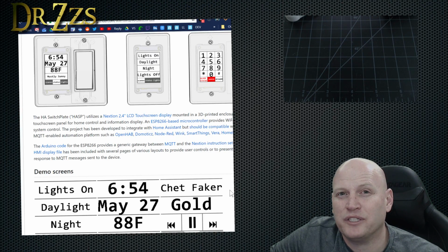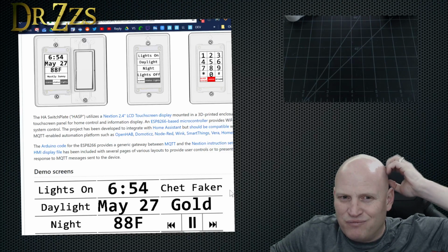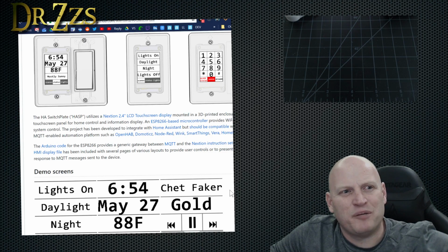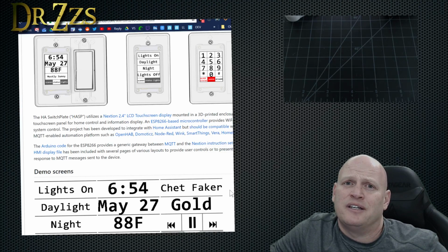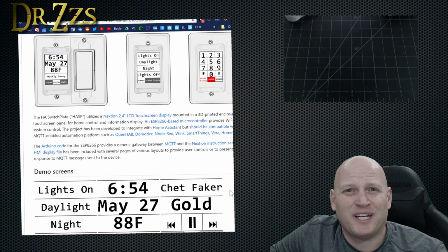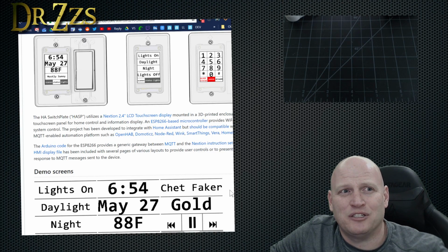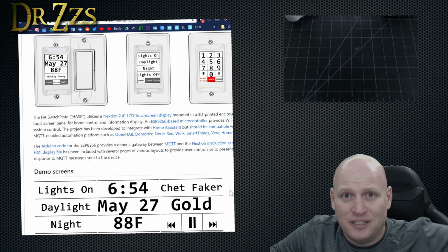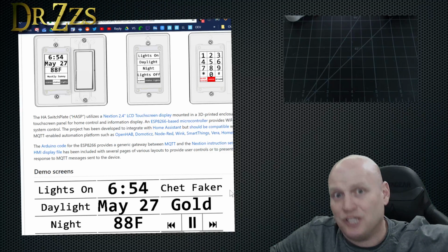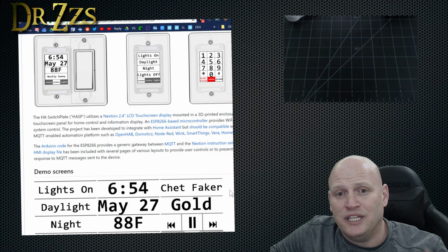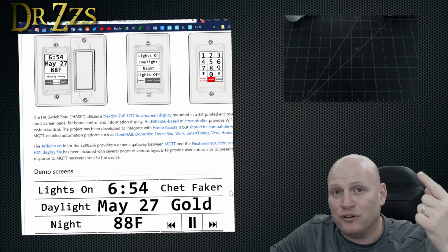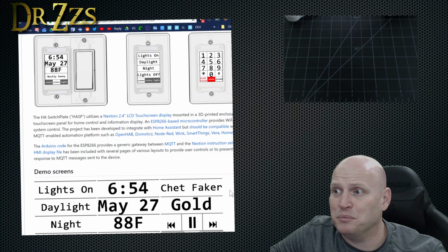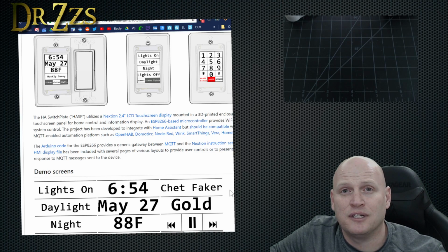I don't think you're going to find a smart switch. You've probably seen that video where I kind of tried to explain that. If you open up your switch box and all you have is 2 wires coming to your regular light switch that goes on and off, then you're going to have a real problem trying to get anything smart in that box, because what you have in that box then is just hot, really. It's a hot wire that's coming from the lights, switching and going back up to the lights. So the easy solution is to put the smart part, the Sonoff or something else, up where your lights are. If you're in the Facebook group, Chris Brooks, he showed an example of that problem and how he fixed it.